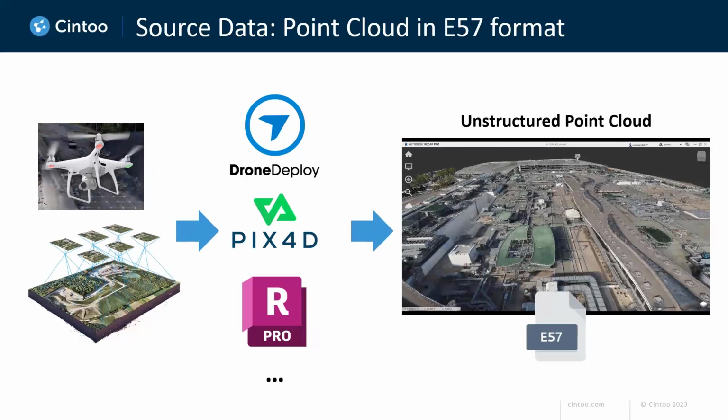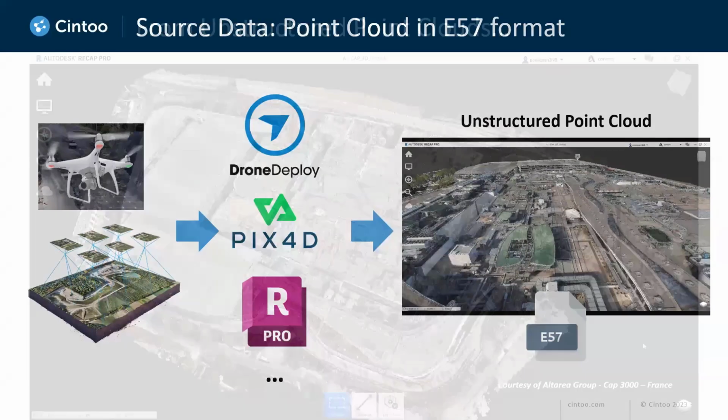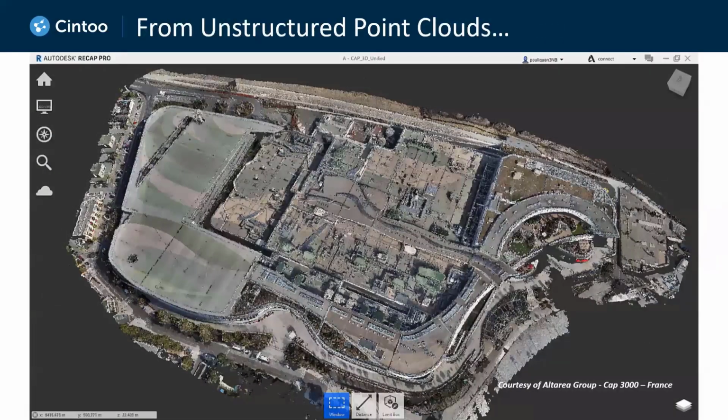If you have only LAS data, it's very easy to convert LAS to E57. In our documentation, we do provide two easy ways to convert your LAS files into E57, before we support LAS as well, which will come in the next few months. Either you use Recap or you use CloudCompare to turn your LAS files into E57. So you end up with an E57 point cloud.